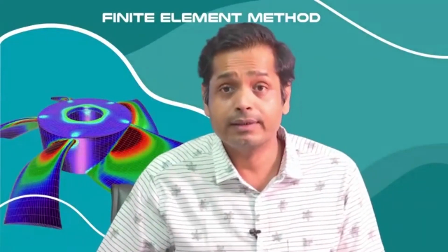Hello everyone, today is the second day of this week. In the last class we had seen how to derive the weak formulation for a scalar-valued two-dimensional problem, and we also saw how to develop a finite element framework based on the weak form. We wrote the general form of the element level equations, and then we also discussed how to determine the individual terms in that equation.